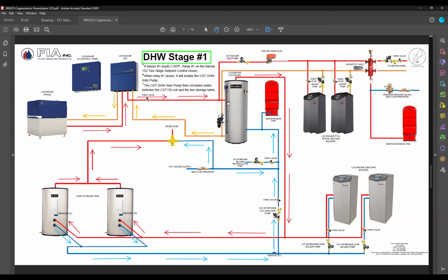So whether it's heat pumps, where you want to reduce the number of cycles on the compressor, or even boilers, you want to reduce those number of cycles. So how do we do that with a water system? That's when it gets really important to understand the sequence of a system, what enables what, and how things are controlled. In this case, I said, all right, we've got a building with space heating the whole fall and winter, the unit's going to be cranking away. How do I get it so that this thing is going to be running other than in the heating season?